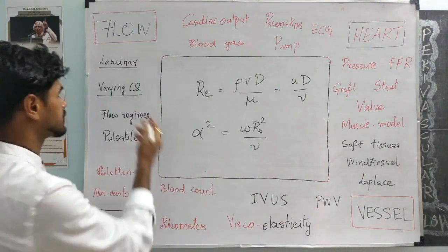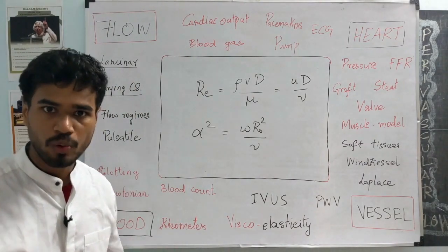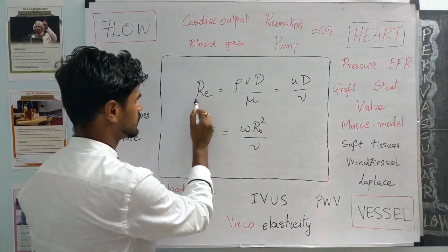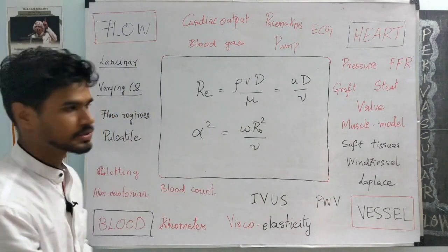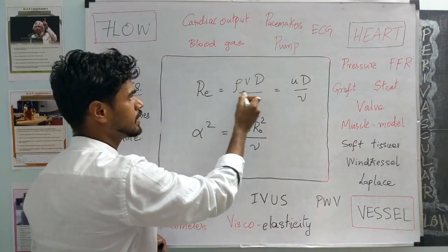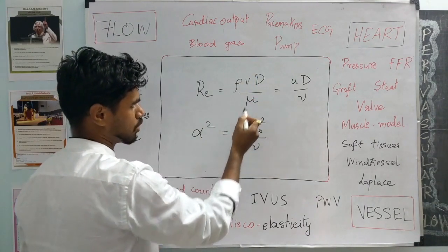See, as we are making assumptions like laminar and steady state and all that, we want to make sure those assumptions hold good for the problem of interest. And that's why we need to always check. These two non-dimensional numbers are of great importance. First is the Reynolds number, the ratio between the inertial forces at the top and the viscous forces at the bottom.